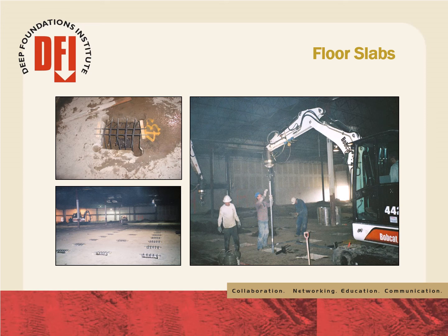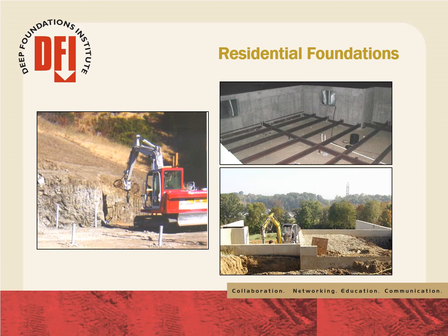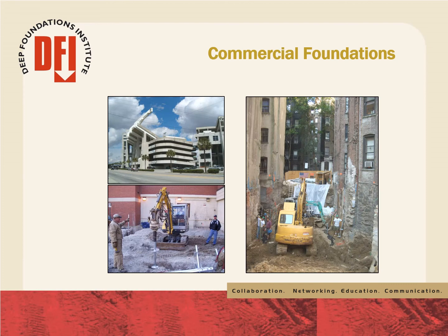Helical piles installed to support structural slab inside existing building. Helical piles being installed to support single-family and multifamily structures, including structural slabs in regions with heaving soils. Helical pile installations are vibration-free, making them a viable solution for projects with close proximity to existing structures.